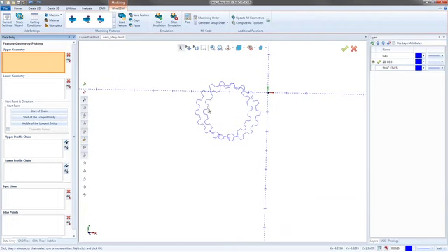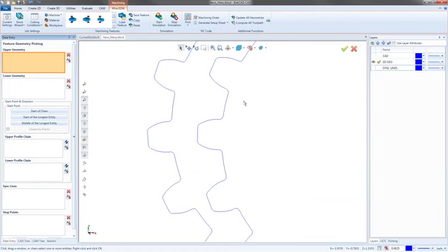So I'm just going to hold shift. And I'm specifically clicking on a specific point of this line. So if this is the midpoint, I'm going before the midpoint. And then I hold shift and click. And the reason I did that was because when you click, depending on which side of the line you're on, when you hold shift and click, it'll actually send the chain a specific direction. So if I hold shift and click right here, it sends the chain around the part this way. So it'd go all the way around and then eventually come back here.